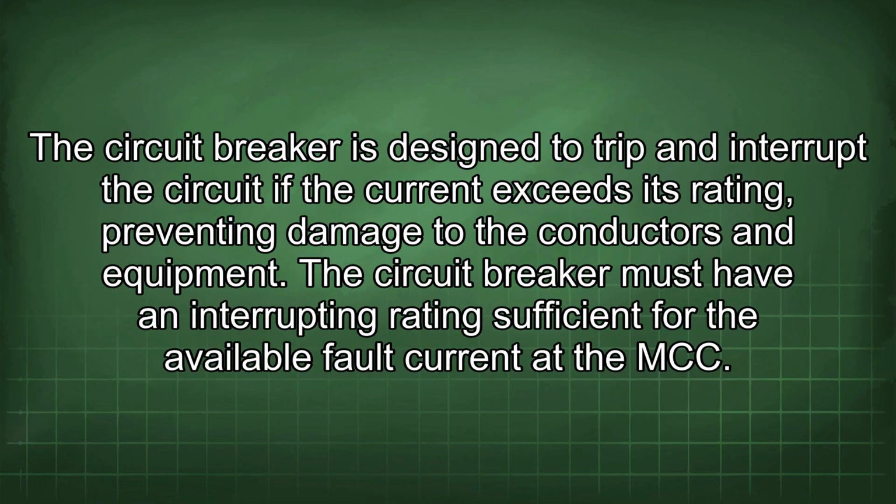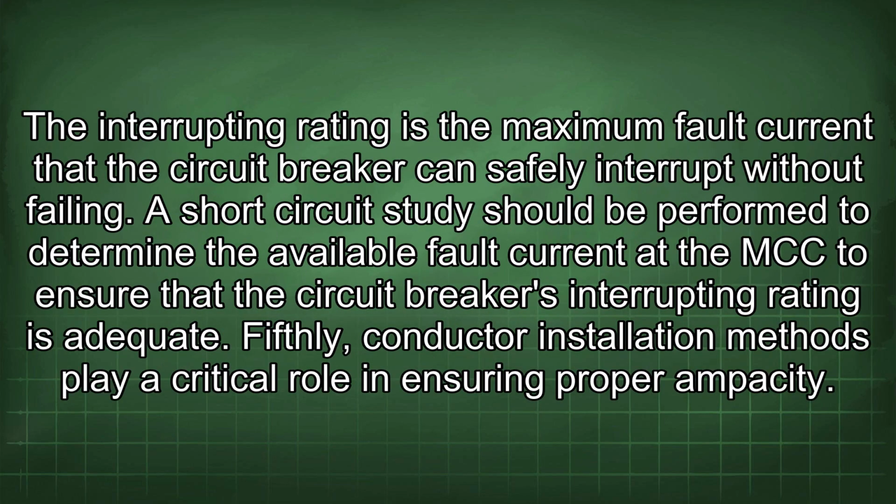The circuit breaker is designed to trip and interrupt the circuit if the current exceeds its rating, preventing damage to the conductors and equipment. The circuit breaker must have an interrupting rating sufficient for the available fault current at the MCC. The interrupting rating is the maximum fault current that the circuit breaker can safely interrupt without failing. A short circuit study should be performed to determine the available fault current at the MCC to ensure that the circuit breaker's interrupting rating is adequate.